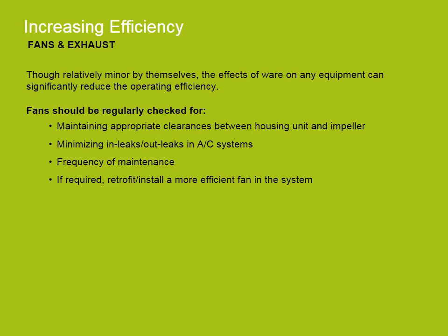Though relatively minor by themselves, the effects of wear on any equipment can significantly reduce the operating efficiency. Fans should be regularly checked for appropriate clearances between the housing unit and the impeller, minimizing in leaks and out leaks in the air conditioning system. It is important that all fans are frequently maintained to ensure they operate efficiently. If required, a more efficient fan should be installed or retrofitted.